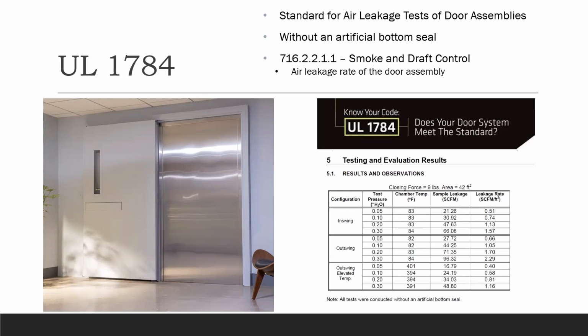Okay, so I bring in another door and I say all of these components have been tested together. It is an integrated system, but I'm just going to add an automatic door bottom later. That also would not work. You couldn't add a conventional door sweep later. It would have had to have already been tested with the system prior to going into the opening. So really, you would need a completely integrated door system that's been, 1, tested completely together, and 2, with a sweeper seal that has already been tested with it to go in front of those openings.